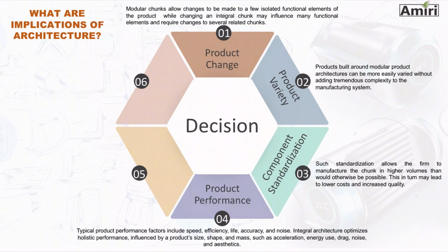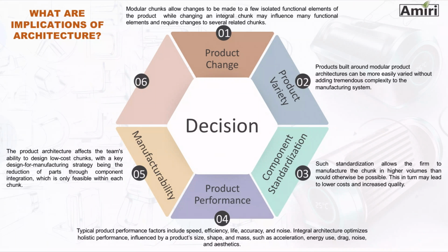And it allows for geometric nesting of components and this minimizes the volume that the product occupies, and overall, enhances the performance of the product. This function sharing and nesting kind of allows use of material also to be minimized, and potentially reducing the cost of manufacturing the product, which brings us to the next one, which is manufacturability.